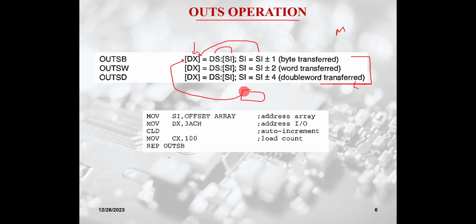But 8086 doesn't really support direct memory to memory data transfer. Okay, so there has to be some register which comes into play in between. Okay, but that is not evident in this software, in these commands. Okay, so this is just to make the life of the software engineer a bit more comfortable. That's all.